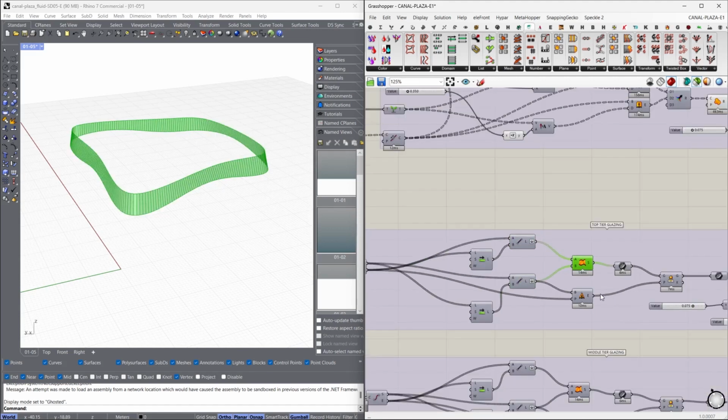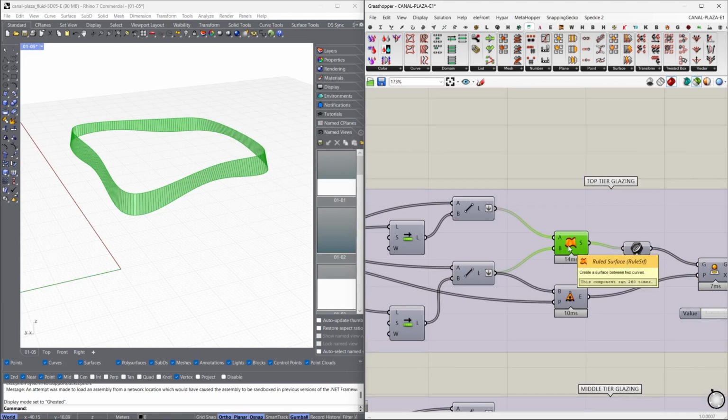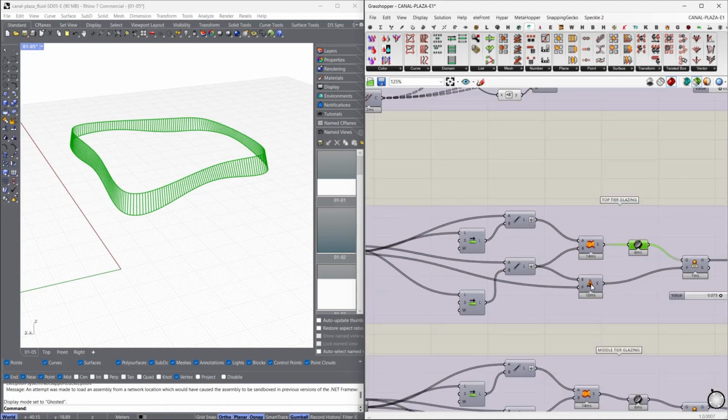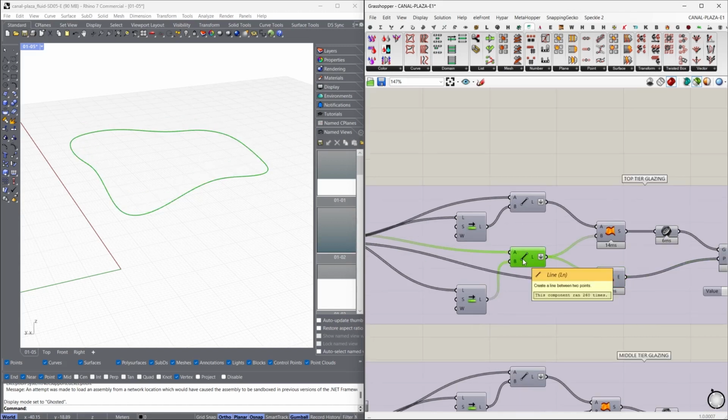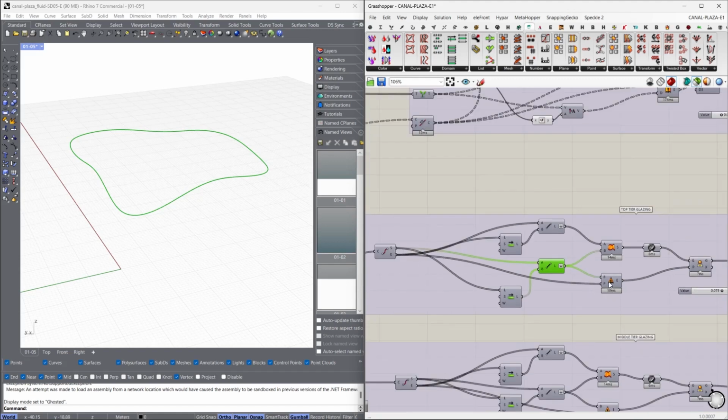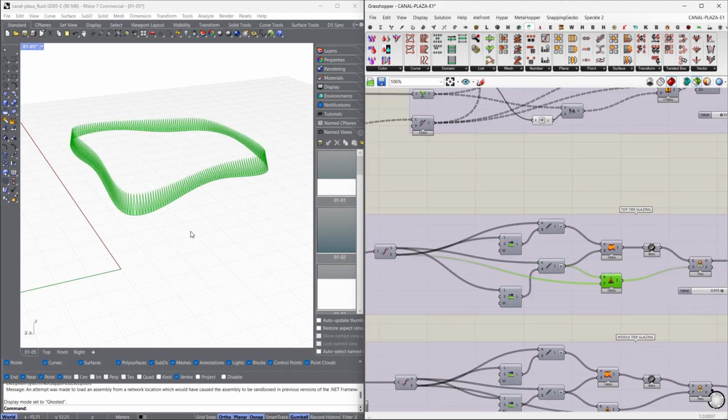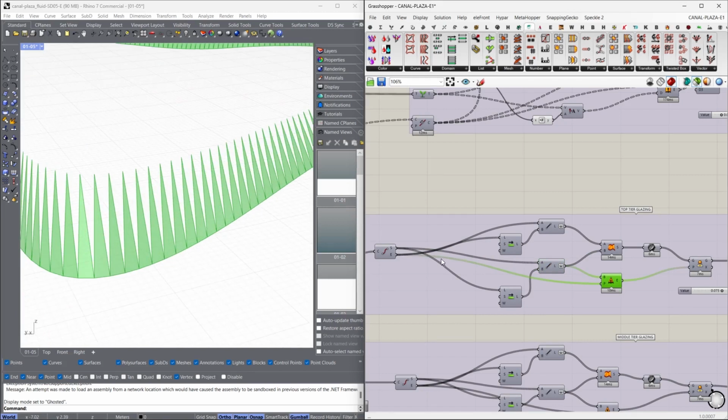And now we've got these planes, which aren't fully planar, but fortunately Grasshopper recognized the outlines. I just used the curve component and it recognized the outlines. But then what I did is, because 3 points are always planar, like a table with 3 legs never wobbles because they always touch the ground, I took basically the base lines which we generated, and then I took the end point on top, one of the end points, and I generated these planar triangles.